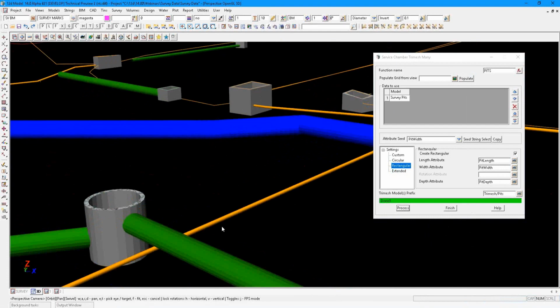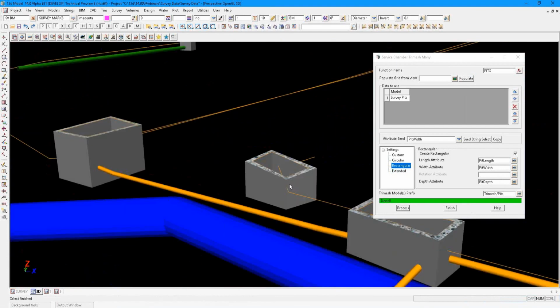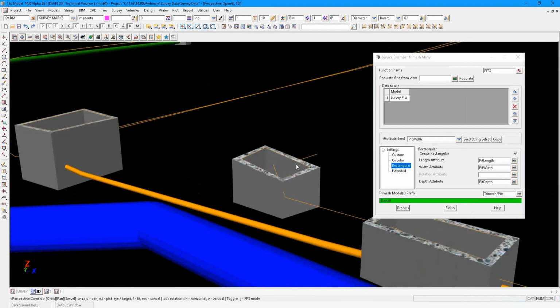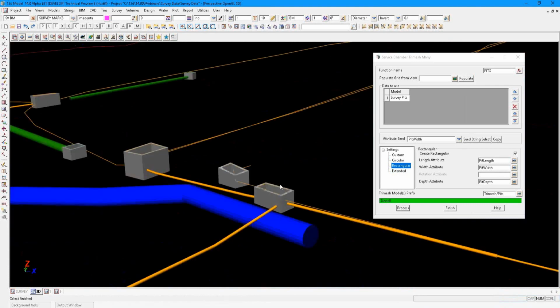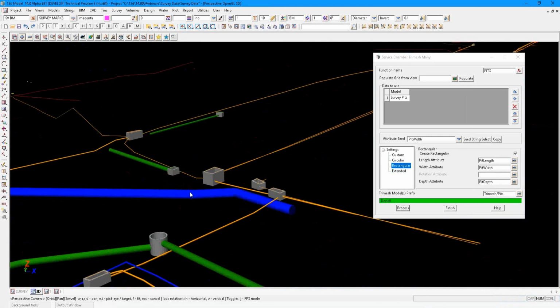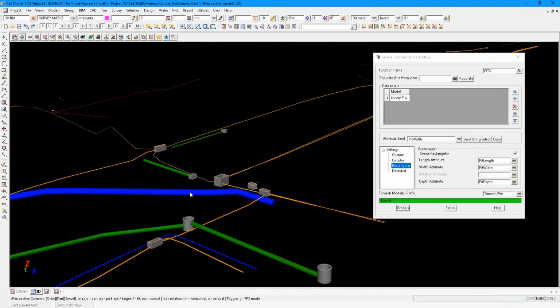If you've got a height wrong or if there's a bit of a slope on the pit, it will also get the shape from that. The depth is taken from, I think, the first point on the string. So whatever the depth is, it's always taken from the first point, and then pushed down. Now you've got the ability to have those 3D pits, so it really does complete the model.